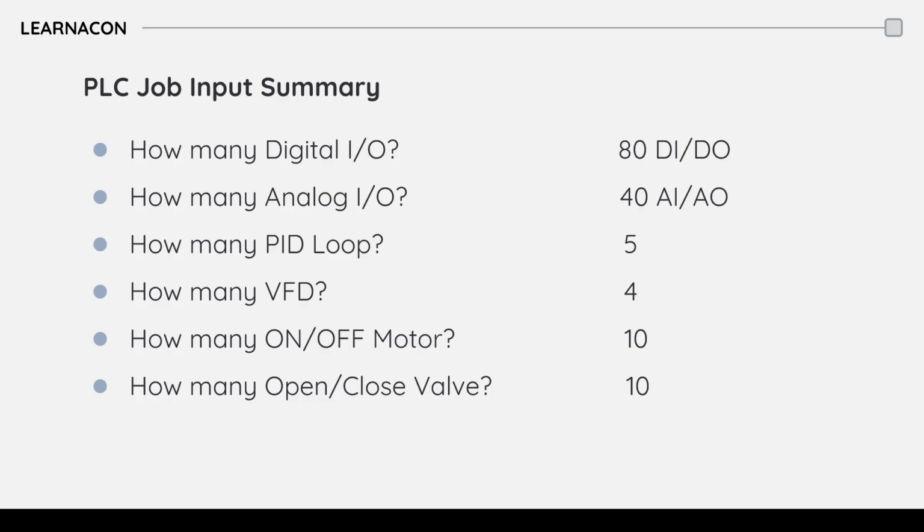Finally, and most importantly, we define the major equipment sequences. This is the core logic that dictates how all the individual components work together to perform a process from start to finish, such as a CIP or clean-in-place skid. In this project, we have 2 main operational sequences to develop.